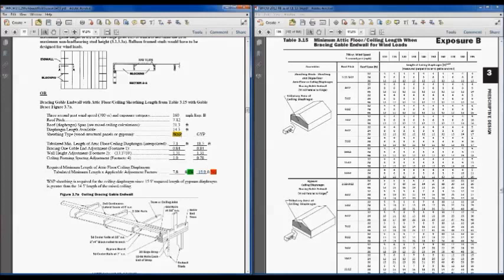So we're going to end up having to sheathe that ceiling assembly with wood structural panels because of all the adjustments that we have to apply to this particular example. So I'll have to go back and look and see with that particular example why that number is not working out for me. But for the wood structural panels, when we come up here and look and interpolate like we did before, we're going to have plenty of capacity. Oh, I know what it is.